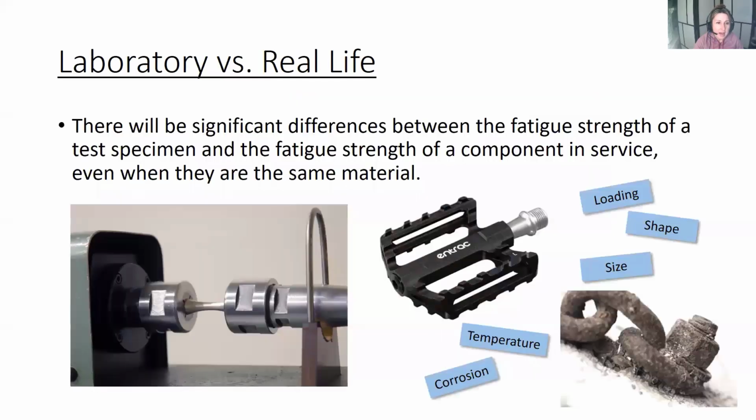Once you're finished with that, we'll come back, and the next thing to consider is this difference between components in the laboratory under fatigue loading versus components in real life under fatigue loading. And there will be very significant differences between the fatigue strength of a test specimen, so something that is polished and perfect.